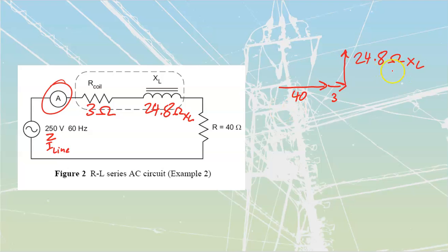Once again, if we are taking a look at XLs and Rs, we know that resistance is always along the x-axis, and because of this, ELI, that voltage leads the current for an inductive circuit, and because my current is always in line with my resistance, that means my inductive voltage would be going upwards, which means inductive components, we're always treating those as going upwards.